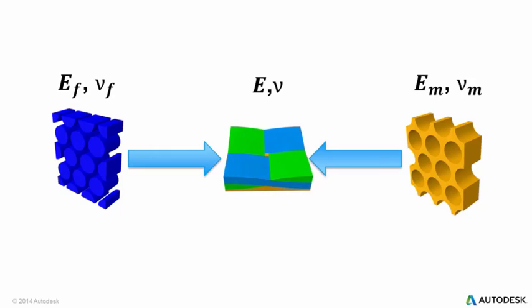Working at the fiber and matrix level allows various modes of damage to be identified in either tow, which will result in different responses of the composite material in the finite element analysis, resulting in physically realistic damage propagation.